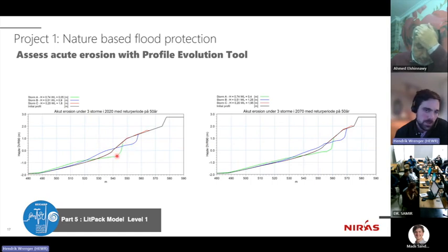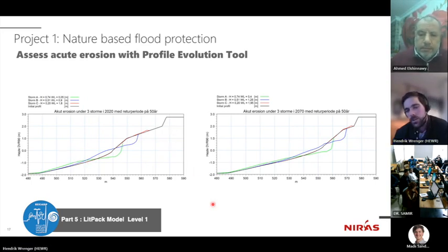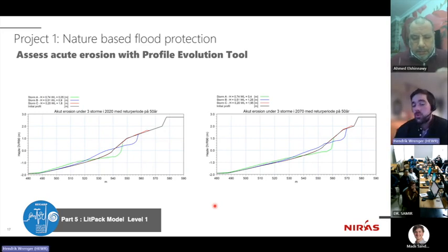So this green storm might be a little bit on the edge, meaning that large amounts of material are lost to offshore. Because if large amounts of material are lost to offshore, they cannot be transported along the beach anymore. They cannot be reestablished anymore. So then it's up to the engineer to judge how often do we have storm events where large amounts of material are lost to offshore.